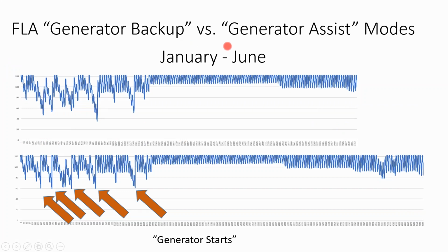So here we have January through June, and we see that we're starting to go into some times where there's not enough sunlight for the array to charge back up. And we're getting down to about a 50% depth of discharge at this point, before the sun comes back and barely almost charges the array all the way up to the top, and then the clouds come back, and then we charge back up, and the clouds come back on a multi-day weather cycle.